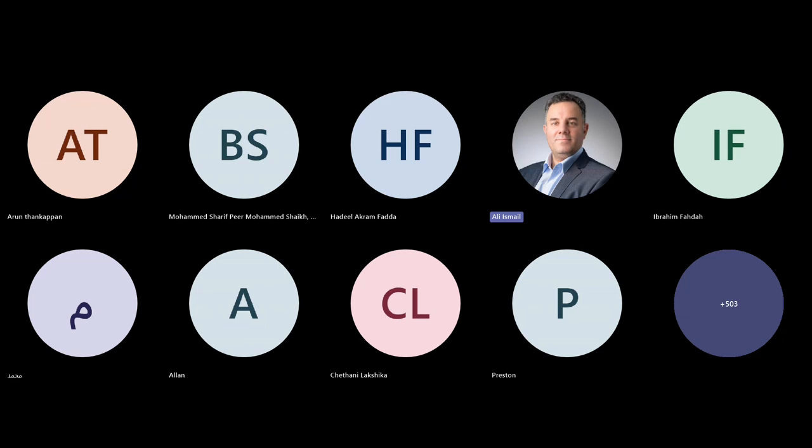There are many tools which give you opportunities to filter and check your models in a good way. Now, the question: why may I need to understand the IFC standard particularly? Because knowledge is power. If you are dealing with an IFC model as a black box and you don't know how the information is structured, you are losing a big chance to benefit from the information inside this model, or to understand how it is arranged, or to pick up some problems and solve them correctly.